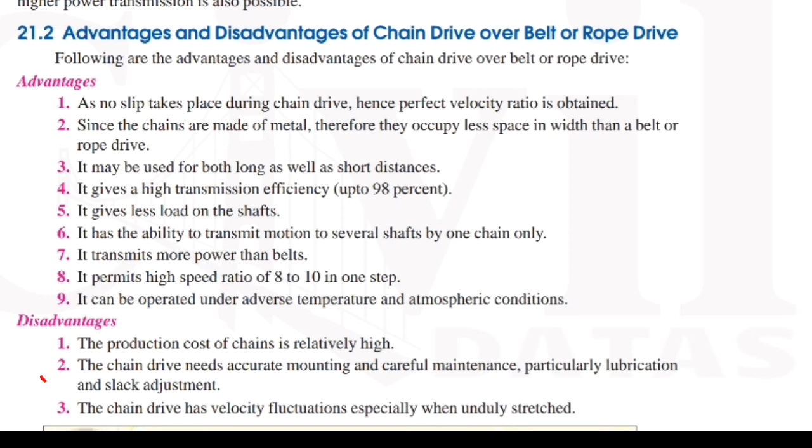And second, chain drives need accurate monitoring and careful maintenance, particularly lubrication and slack adjustment. It is also one of the disadvantages compared to belt drives, because in belt drives we do not use any type of lubricant. And finally, third, chain drives have velocity fluctuation, especially when unduly stretched. These are the major disadvantages of